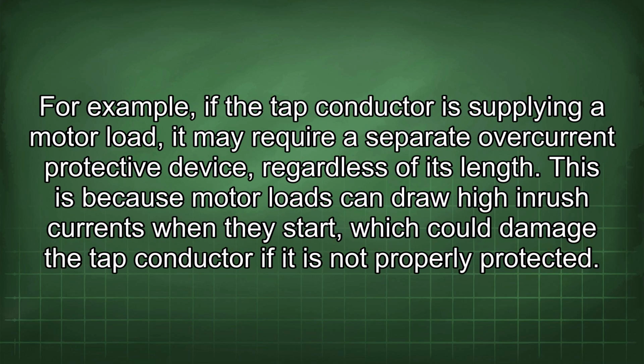For example, if the tap conductor is supplying a motor load, it may require a separate overcurrent protective device regardless of its length. This is because motor loads can draw high inrush currents when they start, which could damage the tap conductor if it is not properly protected.